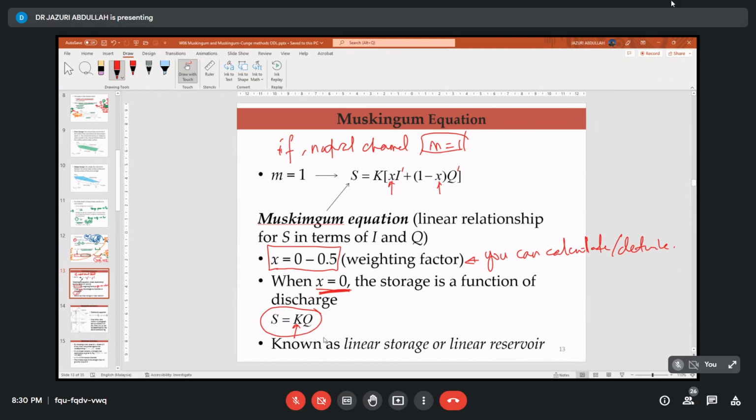So kalau kita tengok X tu sebagai 0, but it's very hard to get X equal to 0. Selalunya X tak akan dapat sampai 0 sebab we have to remember sungai ni dia tidak bertindak secara berapa Q masuk, itu yang akan dapat Q di hujung sana. Tak, selalunya kita akan dapat the discharge at point A, the discharge at point B will be different. So, but if you measure in the short distance, katalah setakat 2-3 meter, yes, you akan dapat benda yang sama. Tapi bila you over some distance, let's say you measure for maybe 100 meter apart, so you akan dapati dia punya Q akan berbeza.